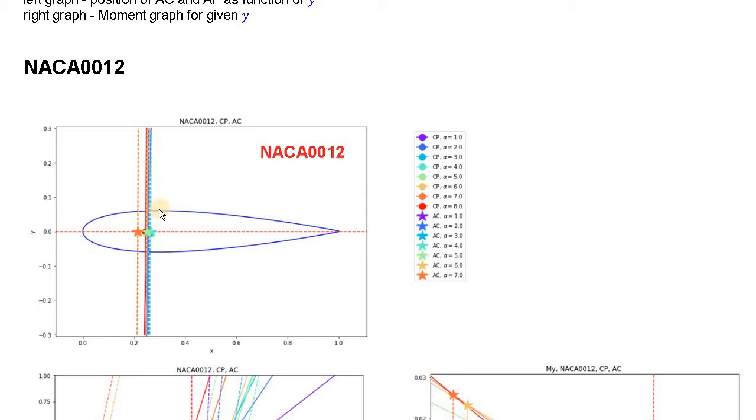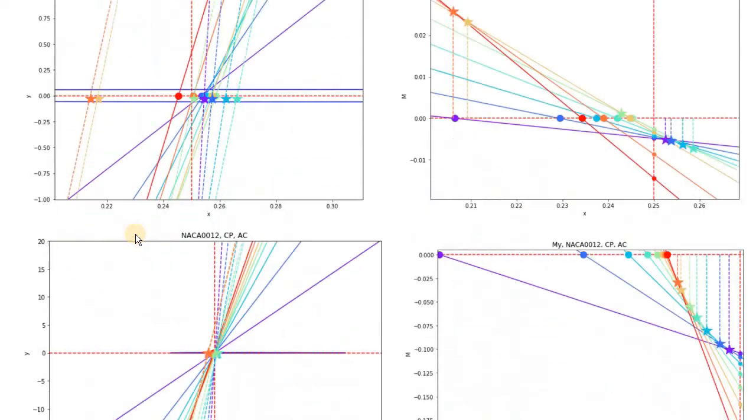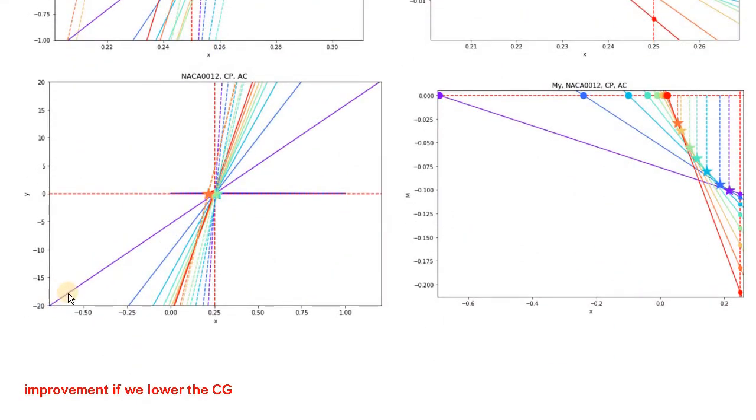Well, think about the lift force acting upwards, significantly bigger than the drag force acting in that direction. So you have to find a line such that you're going to have an equal projection on this line, and then you place a normal line to that one. And then you will see, for instance, this line is the line where the moment is equal to 0 for the angle of attack equal to 1 degree. Here is the 0 moment for alpha equal to 2 degrees, and so on.